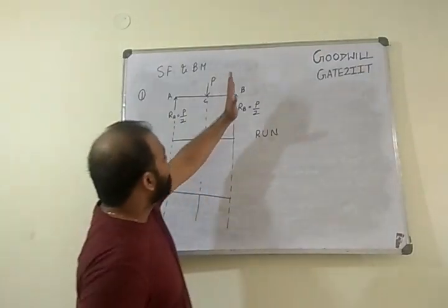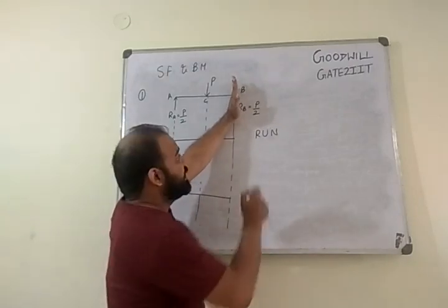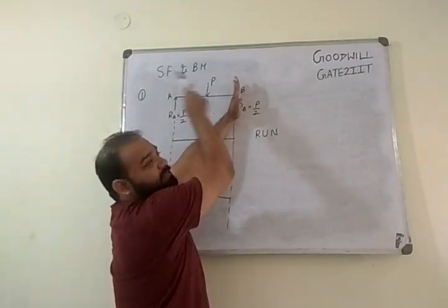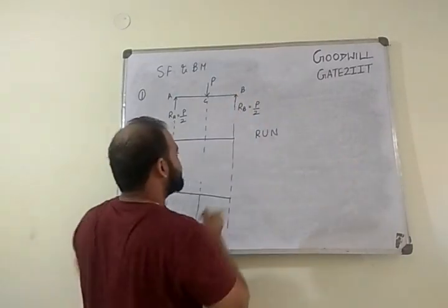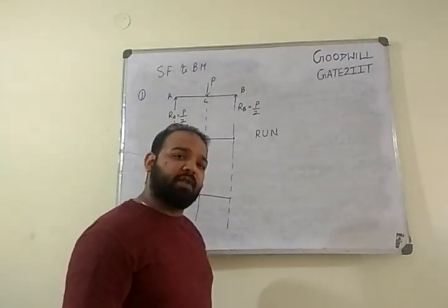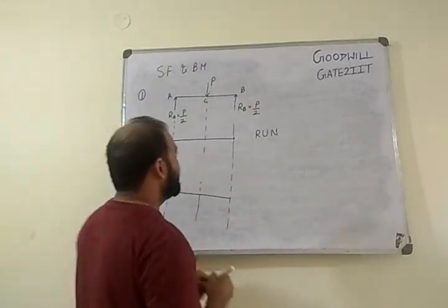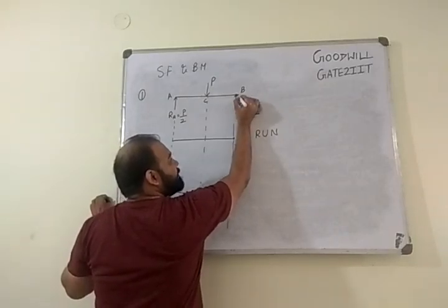For example, I'll stand at point B. So don't see anything on the left hand side, see what you have on the right hand side. I don't have anything. So what should be your shear force? It should be 0. Whatever you have on the right hand side, you need to plot that. Alright. Now, guys, this is kind of an important part.